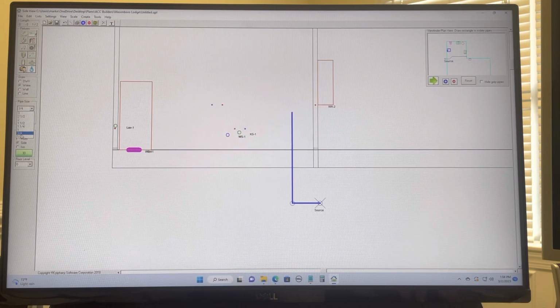I'm going to go ahead and begin branching off of that to create a manifold. I'm going to switch to 1/2-inch pipe because I want 1/2-inch T's coming off of this manifold. Now I've got my first one done. I'm just going to mouse down up there and grab it and drag it all the way down till it bottoms out on the other pipe. And I'm going to do that.